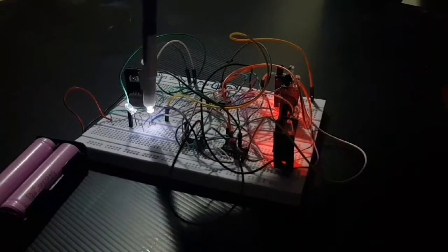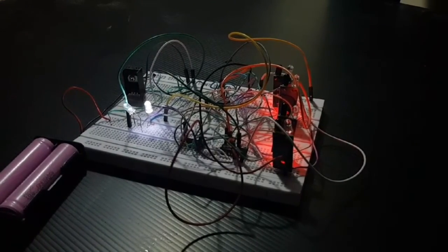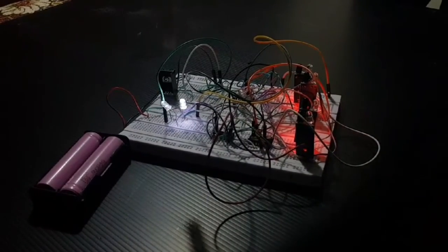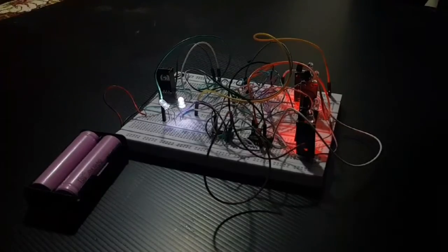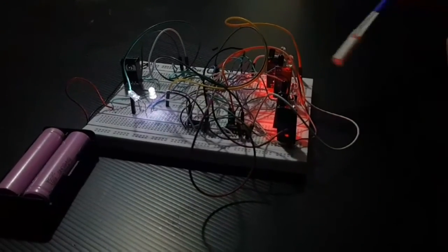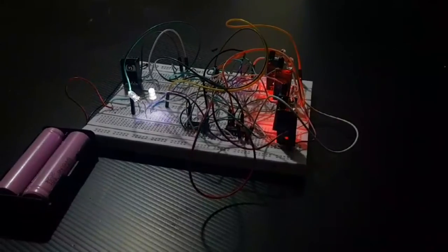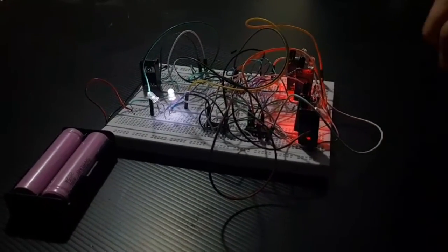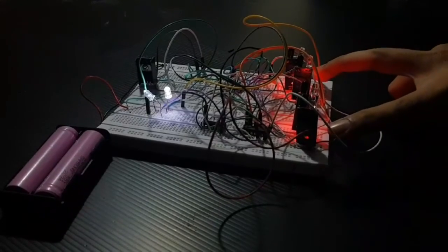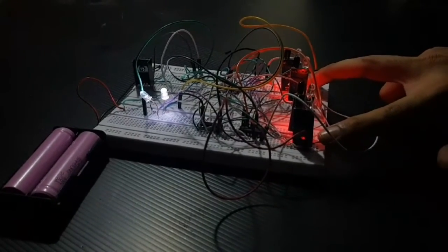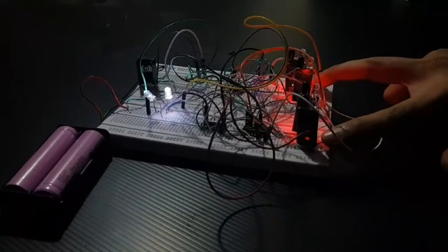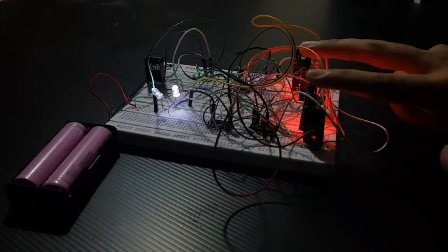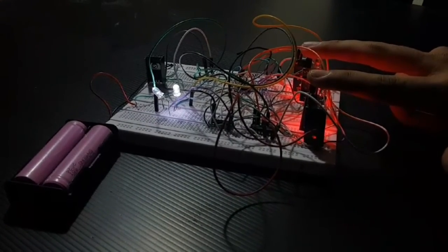So they are moving forward, the motors are on. So if these sensors are sensing a white surface, then the motors are on. A similar case is when both the leftmost and rightmost sensors are sensing white surface, and the center sensors are sensing a black line, then still they will be moving forward.